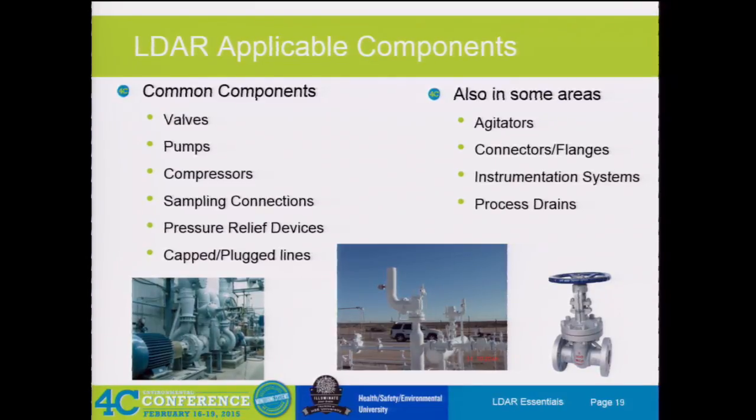But what we're saying here is, I'm trying to figure out how I can mentally paint the picture. You have two valves in place, so you've got your double block system. Your first valve is here, and you actually are running your sample up and over. And then you have your other one. Well, how do I truly purge that system? You can't. So that top valve would still only have a single seat. You would basically have to add another valve to the end.